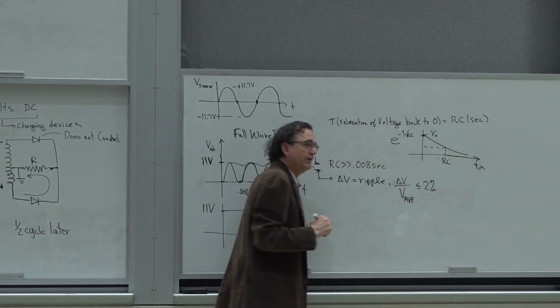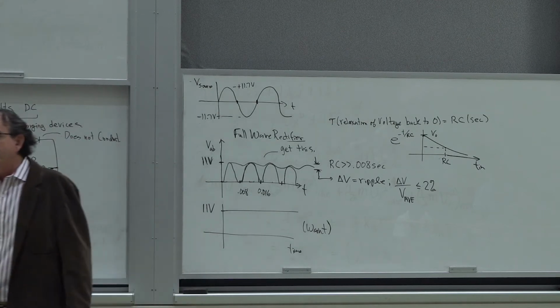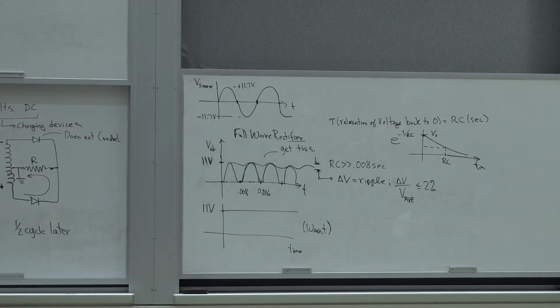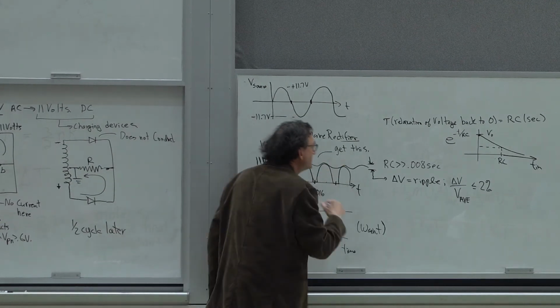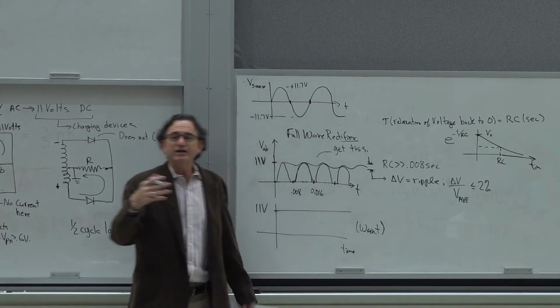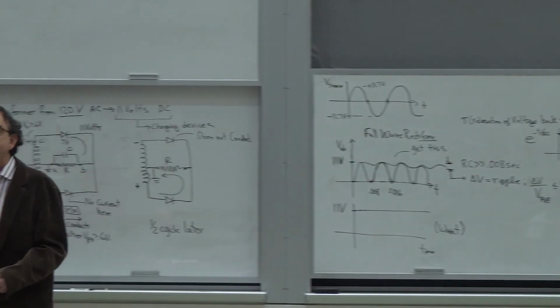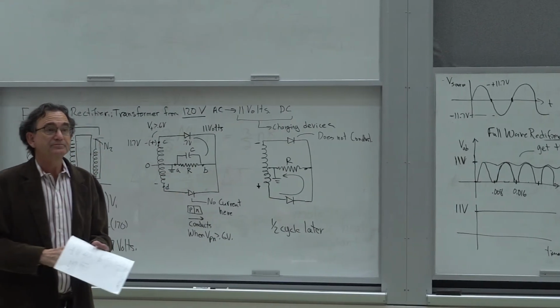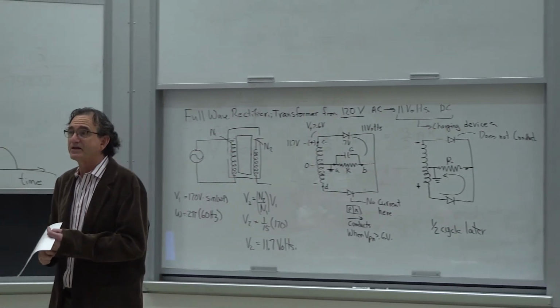So even though it's never going to be exactly completely smooth, it will be approximately smooth. And as long as the voltage is stable to within a couple percent, the electronic device doesn't care and it gets its full charge. Okay? So that's how that works.